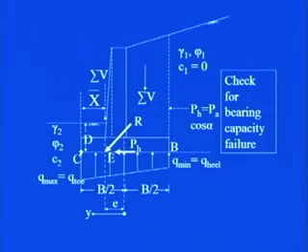This CE distance you can see in this figure is the distance where this resultant R will be acting at this particular point. You see here this dotted line is coming vertically down. Now, if I want to find out its eccentricity from the center of the base slab, I can find out this eccentricity E by subtracting this CE distance from B by 2.